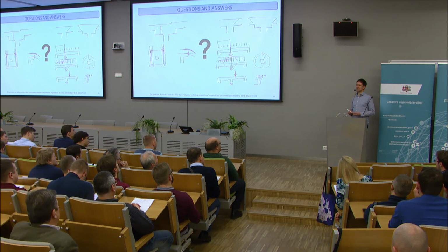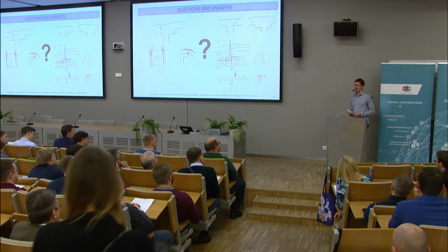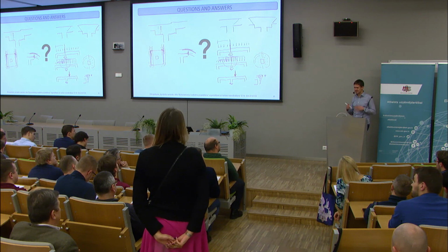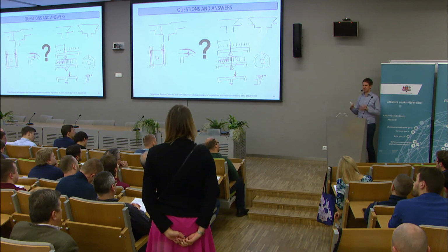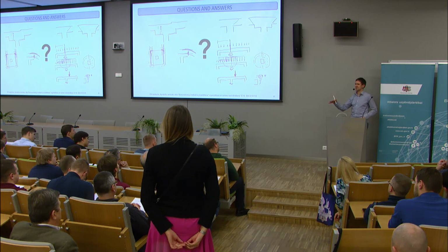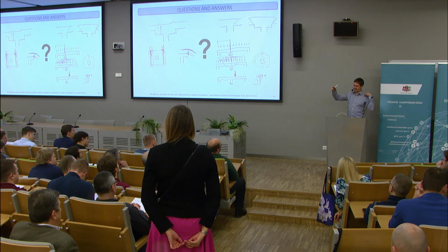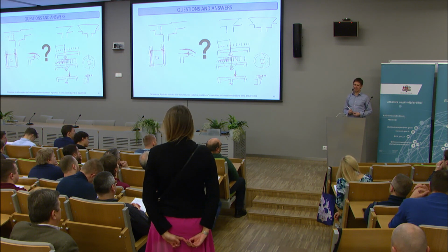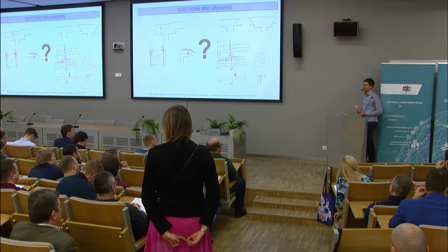It's in agreement with the theory of plasticity, the lower bound theorem. It gives us a distribution of shear, moments, and internal forces. And if we put enough reinforcement to cover the demand at every point, then we are in agreement with the lower bound theorem of the theory of plasticity.